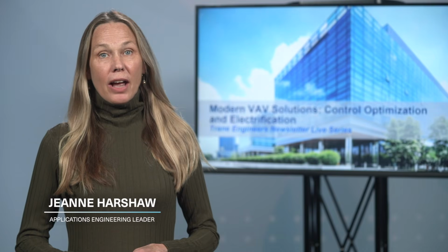I'm Jeanne Harshaw, and today we're going to discuss variable air volume systems. Specifically, we're going to discuss how to optimize and electrify them. Now, VAV systems have been used in our industry for over 50 years because they're efficient. They use a variable speed fan and can use an air side economizer to reduce refrigeration energy. Systems can be designed to provide simultaneous heating and cooling, and they're flexible.